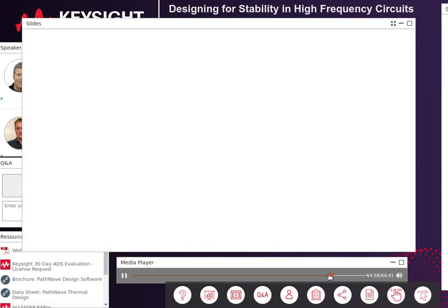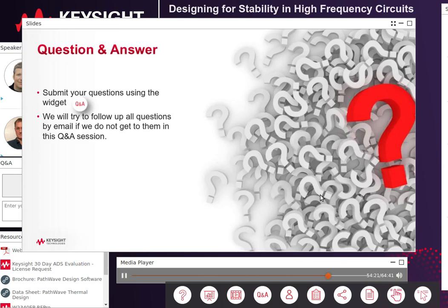The NDF construction, and of course its result. The consequential ability to form the passive network determinant where all the dependent sources have been nullified for normalizing the active network determinant. So I'm a proponent of NDF, but it has some practical challenges. Even if you form the NDF function out of individual return differences, you still need access to the dependent sources in your network. And when your circuit is composed of complex large EM block simulations with sparse frequency points or active S parameter blocks or symbolically defined devices or closed Verilog models, they can pose problems for the NDF construction and of course its resulting numerical stability.